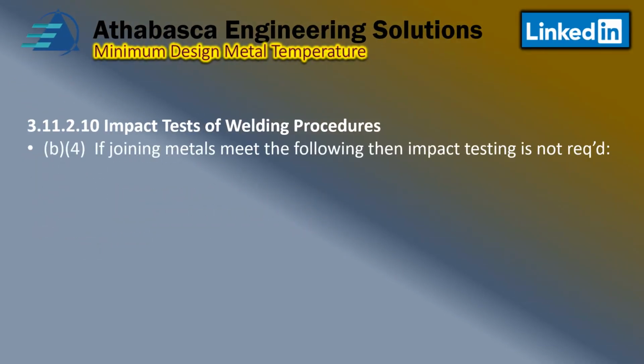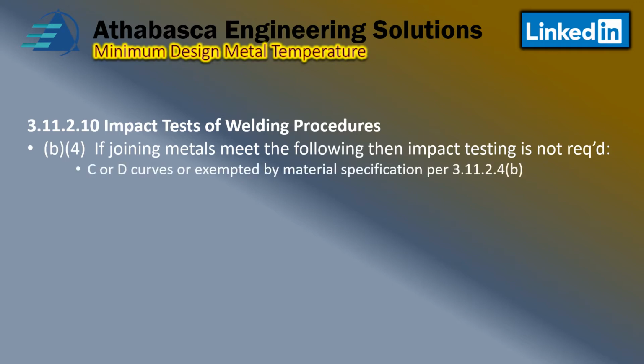B.4 states that impact testing for the joining metals is not required if you have C or D curves, or they're exempted by the material specification. For example, a low temperature forging material, SA 350, but the details are found in 311.2.4b.